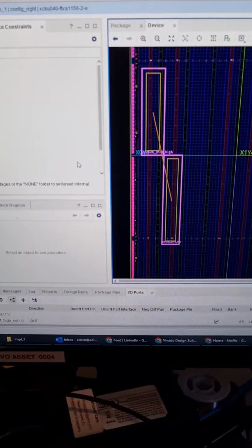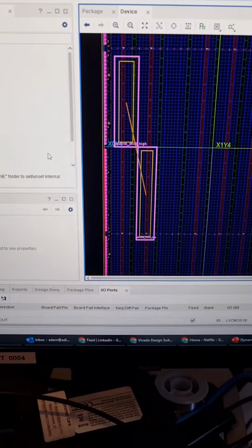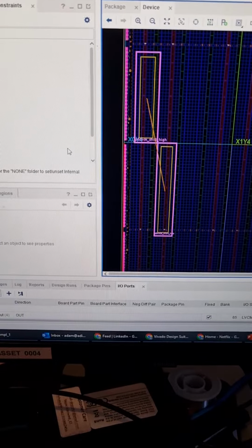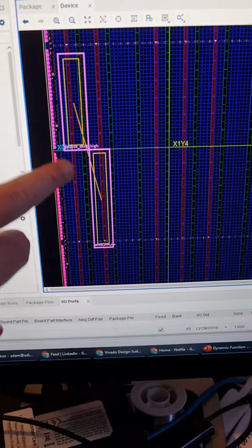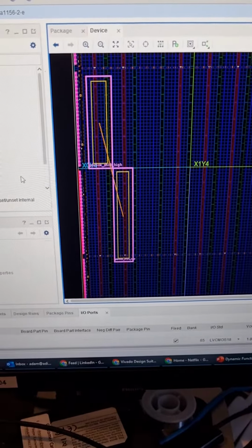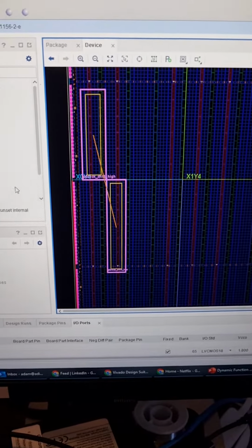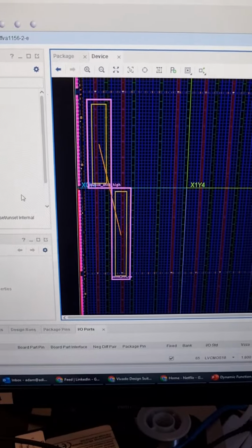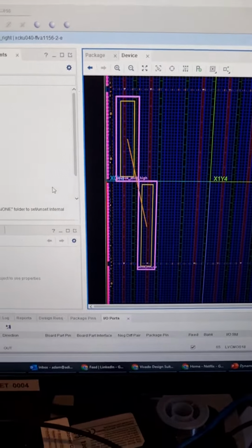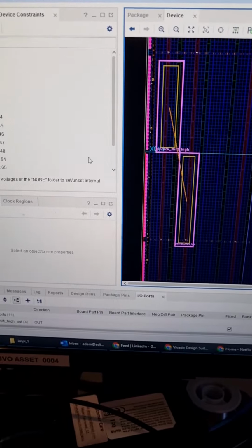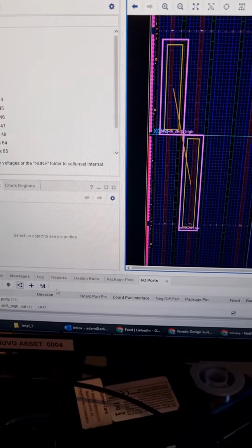So I'm having a little fun this weekend with the KCU105 and working through a few examples of partial reconfiguration. In this example, I've got two partial reconfiguration zones, both of which are just going to be connected to the LEDs on the 105 and show it running through with different patterns. Into this, we've loaded a couple of different patterns, a couple of different partial reconfiguration zones.